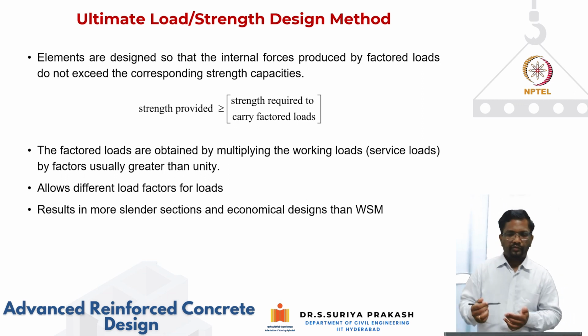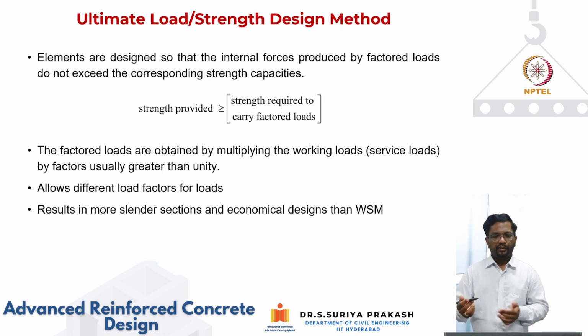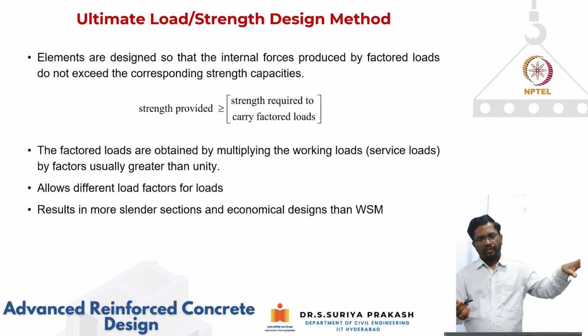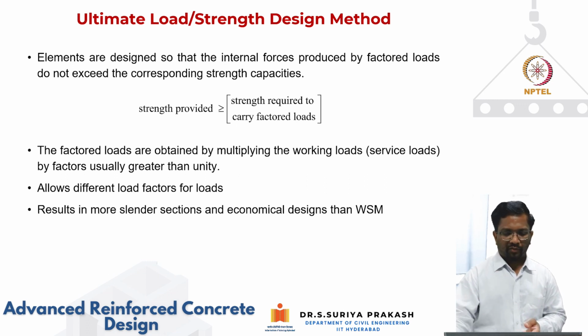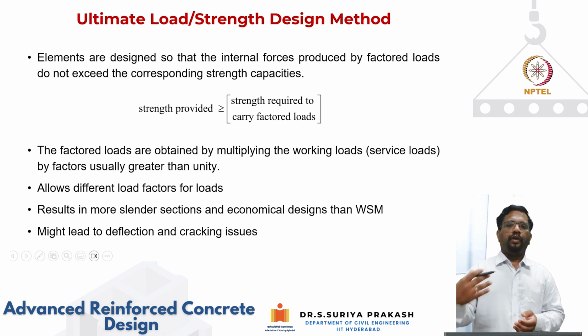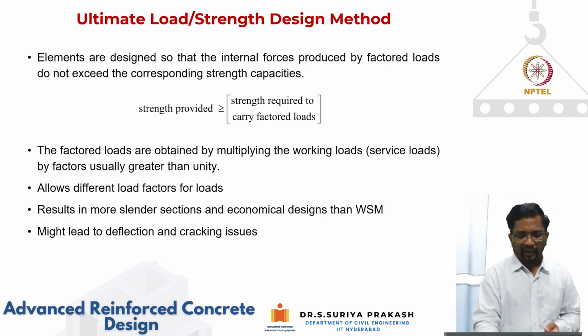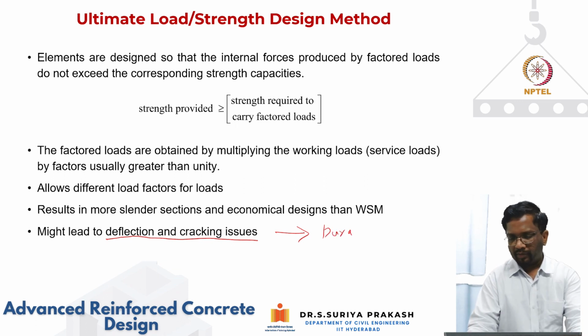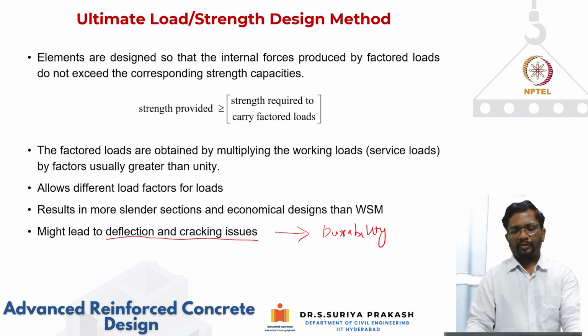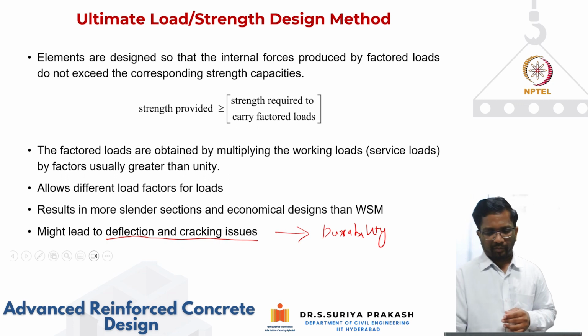Again, what is the drawback of this ultimate load method? As we have seen in working stress, we deal at the serviceability conditions. We don't really check for ultimate. Here, we are designing it for ultimate load condition, but there is no check for serviceability condition. So this is one of the drawbacks of ultimate load method. So it can lead to deflection and cracking issues. Again, the moment you have deflection and cracking, again durability is compromised. Okay, so durability is compromised. That is one thing that you have to keep in mind.